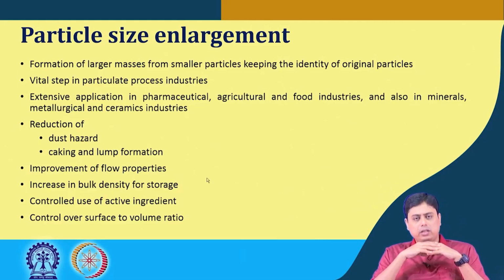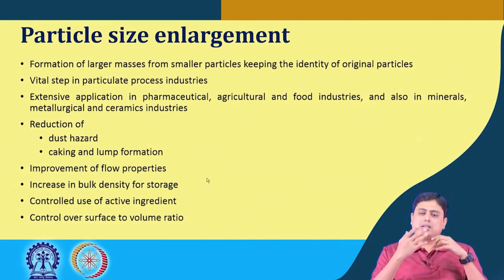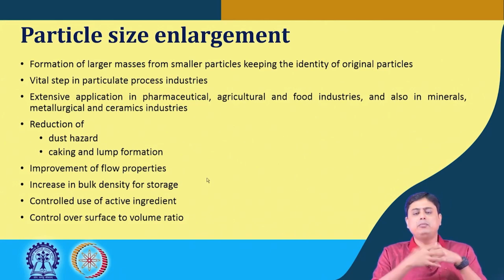Now, the importance of these we have already seen in the last classes. So, not only is size reduction important, size enlargement is equally important in several industries. One of the foremost reasons is the reduction of dust hazard or health hazard with fine particles. The second most important, I would say, is the improvement of flowability.